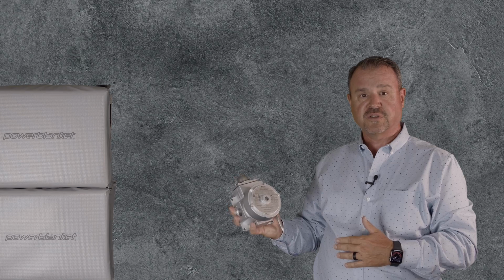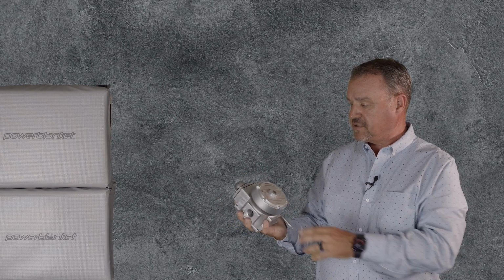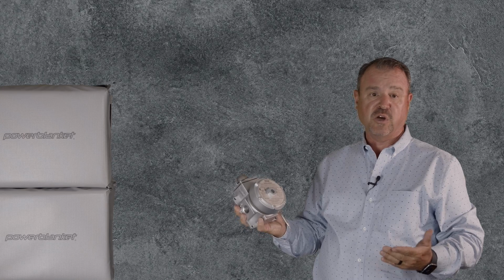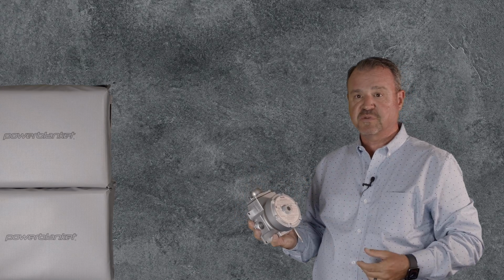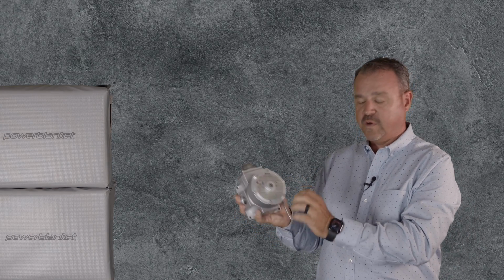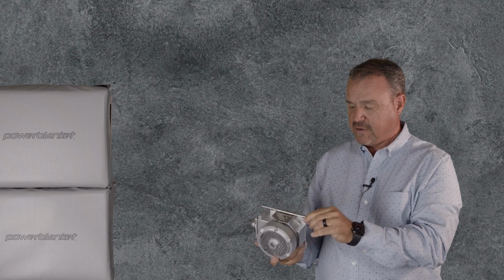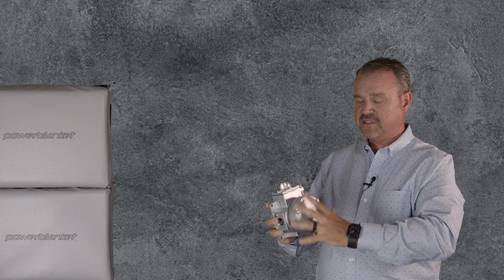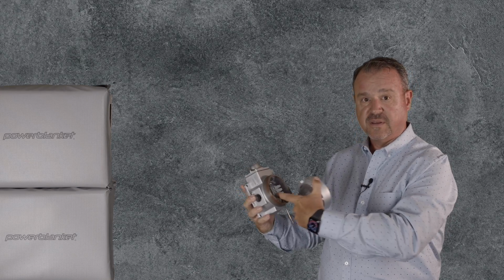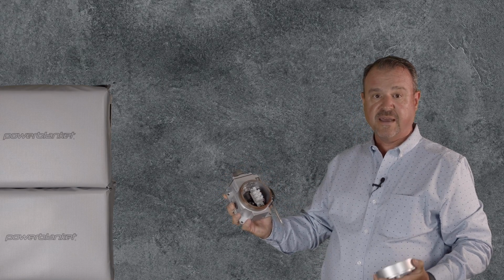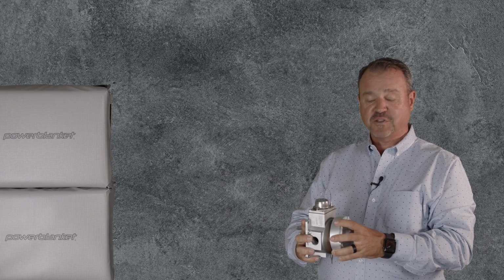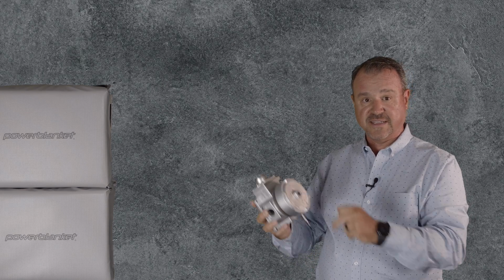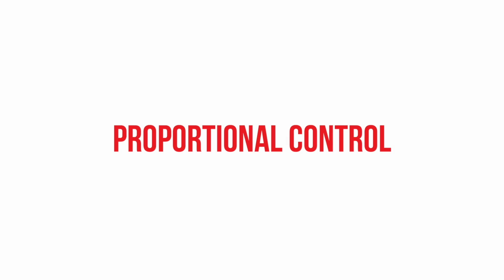On-off temperature controllers also come in this format. This is an on-off temperature controller very commonly used to switch single-phase power loads in heat trace or small heaters, and they come with a bulb and capillary sensor, and the sensor is attached into the controller to a thermostat that's built inside of the unit, and that thermostat has a relay that again allows the power to be gated to the heater to turn it on and off based on the temperature that's set in this controller.